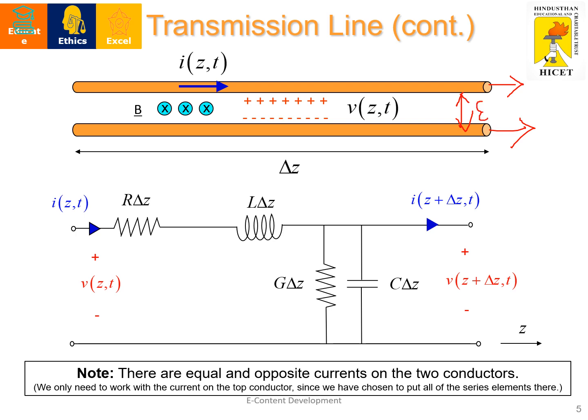As a whole, we'll be getting a capacitance effect based on the diameter as well as the dielectric medium that exists between these two conductors, whereas the length of this particular transmission line constitutes the inductance effect. Based on this, we are obtaining inductance as well as capacitance, and this is the equivalent circuit model of a transmission line.